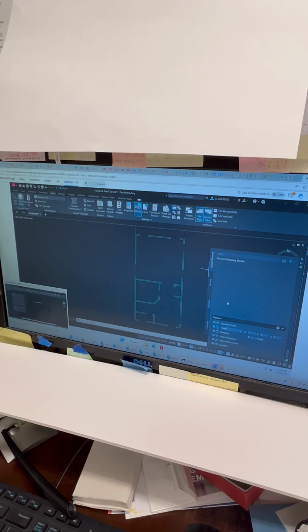All right, the point is 1 foot 6 in the X, and I would put that here. No, you don't want to do all of that. I don't even remember what the other one is. My point is you uncheck that. Turn this on, and it's going to let you take that block and attach it to your cursor. You'll be able to pick anywhere on the screen where you want to place it. You don't have to enter a coordinate.